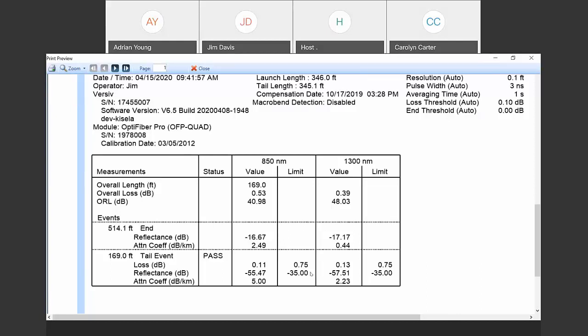There is? And the answer is yes, because I tried to point out, I'm not measuring how much light is coming out of the far end with the OTDR. I'm measuring what is reflected back to me. And we can infer from the OTDR about what the loss is going to be of a link. But for the most accurate measurement of what the loss value is, we want to have a light source on one end and a power meter on the other end to measure how much light is coming out the far end.